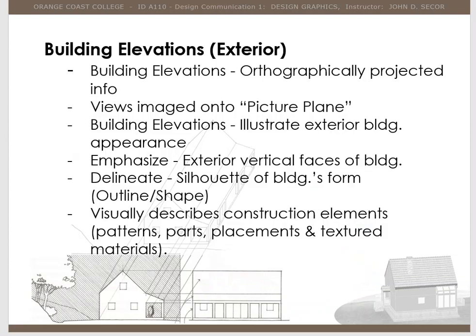So as we continue, the building elevations or exterior elevations, we will orthographically project information. Now, what information? We're going to use information from the plan view or floor plan. And as you create one elevation, you will actually orthographically project from that elevation to create yet another view.